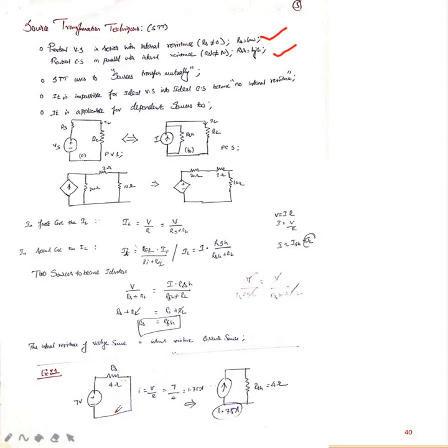4 ohm. So I want to convert it into a current source. Current source means a current with a parallel resistance. You will draw the diagram. What is the resistance value? You can take the same resistance value. These two ohms are equal.